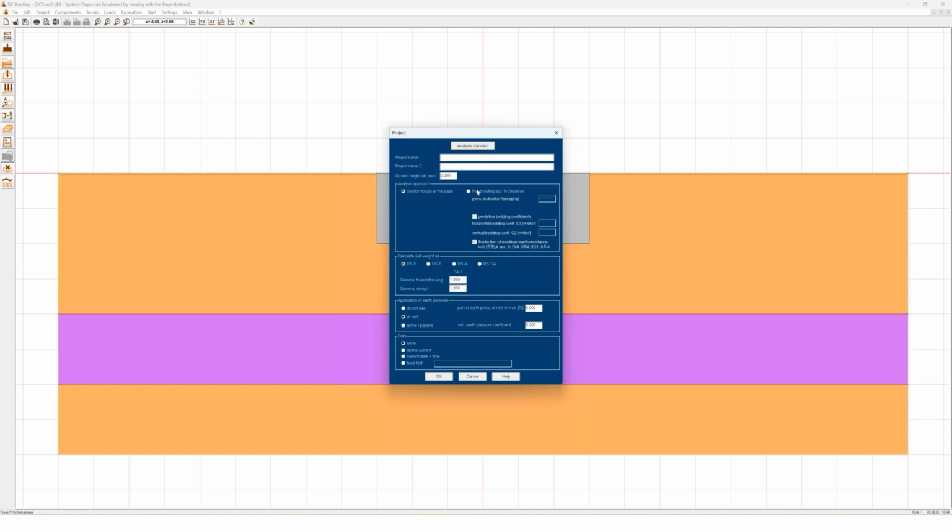The serviceability verification is proved with the inclination of the footing. A bending moment is determined with the given permitted inclination tangent alpha, which you must enter, or it stays the same here. This bending moment from the permitted inclination must be greater than the action. Like, the inclination due to the action must be less than the permitted inclination.